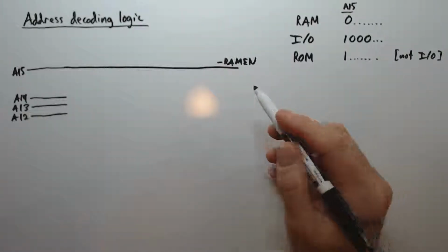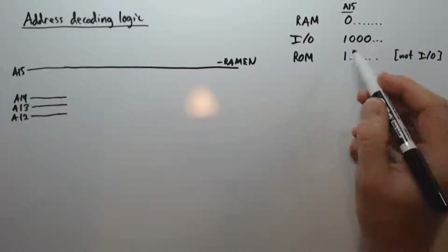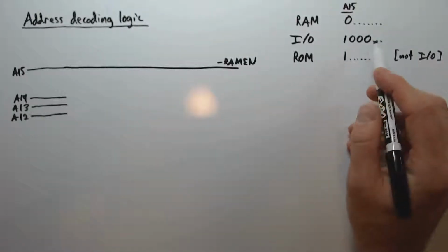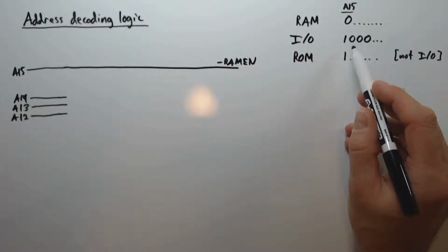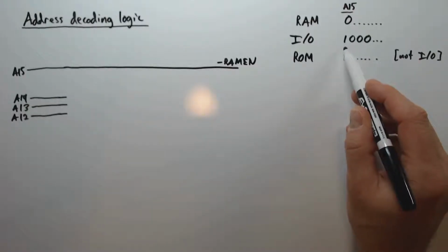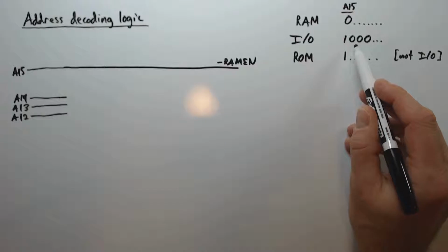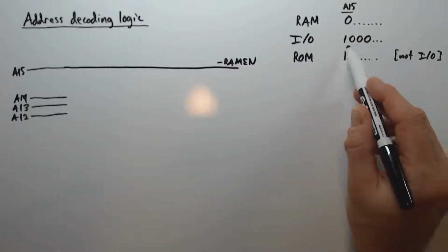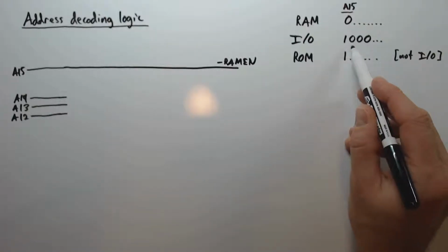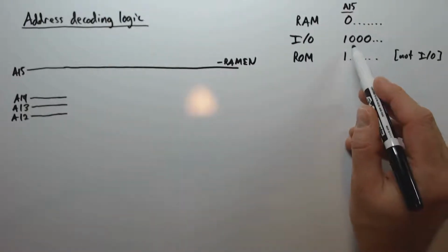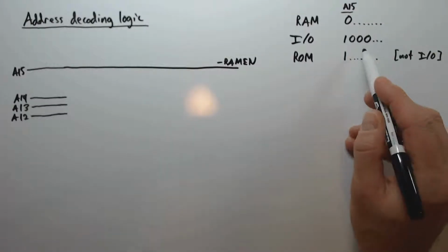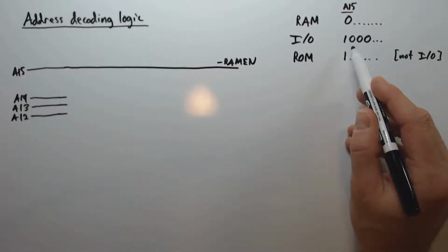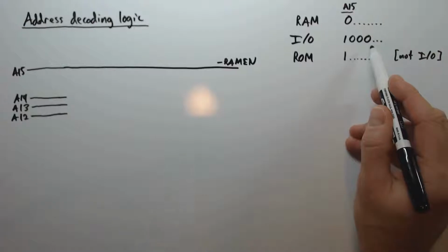All right, so now that we have the RAM taken care of, let's think about how to recognize I/O addresses. And this is sort of two parts. We need addresses which have A15 high and have A14, A13, and A12 all low. So to recognize this particular pattern of zeros in these three signals, either an OR gate or a NOR gate is going to be very helpful, because that distinguishes between the cases where all of these are 0 versus at least one of these being 1.